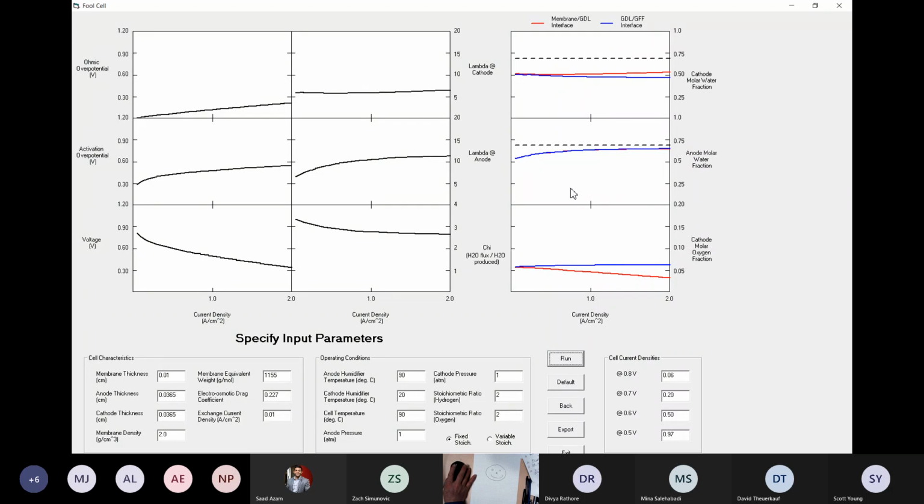Okay, so now I want to know what happens if I'm cheap and I don't want to send hydrogen out into the air wasted. What should I do? Do you have to change the pressures? No. How can I limit the amount of hydrogen I'm wasting? The stoichiometric ratio? Yeah, I have to change my stoichiometric ratio. So let's take the hydrogen down to, what do you think? 1.2 or something. All right, we'll go to 1.2.